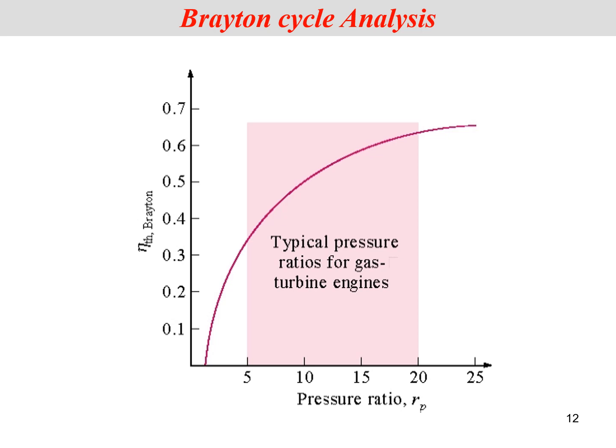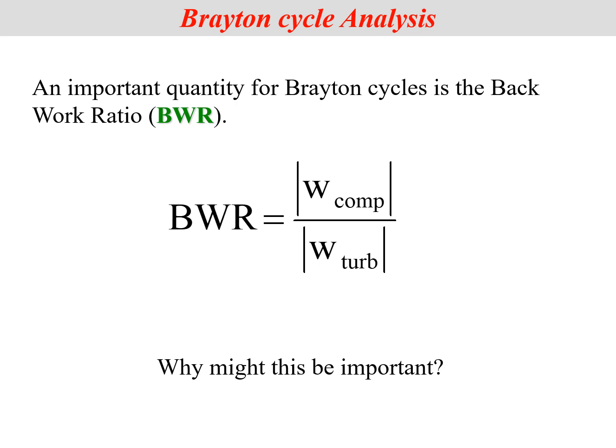So if you take 5 as an example, the efficiency value is this, and if you take the value at 20, this efficiency is this. This figure is not exactly accurate. Right now we have gas turbines which work at pressure ratios of around 50 to 55. So this is a bit out of date, and pressure ratios for modern gas turbines are a lot wider. But you'll see how increasing the pressure ratio beyond a certain point is also not helpful for us in some scenarios.